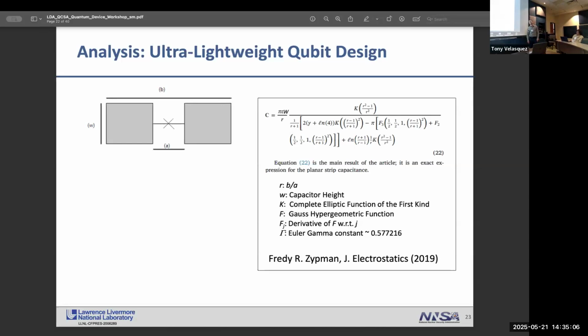So the way we're doing these shadowing processes is that you have two layers of resist, and the top layer is where your primary mask geometry is, and the lower layer is just suspending that mask, holding it in place.